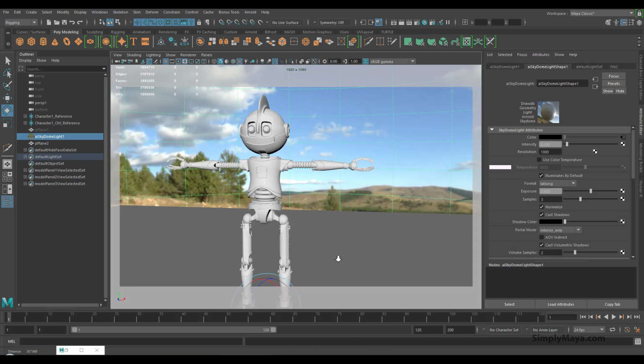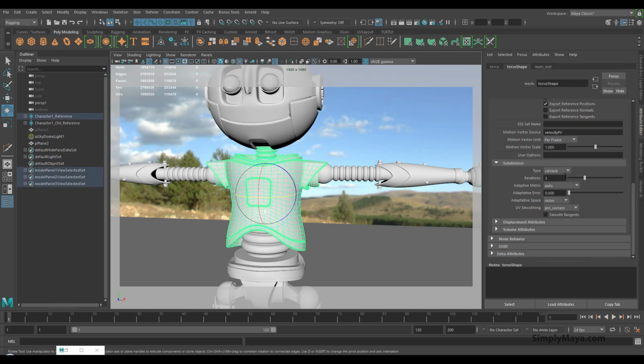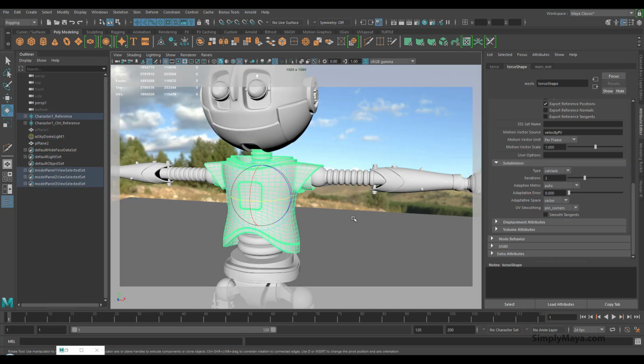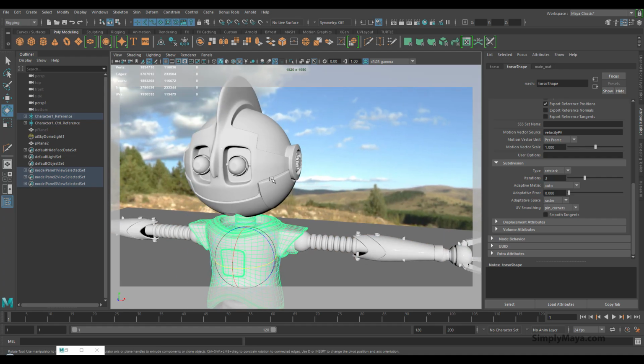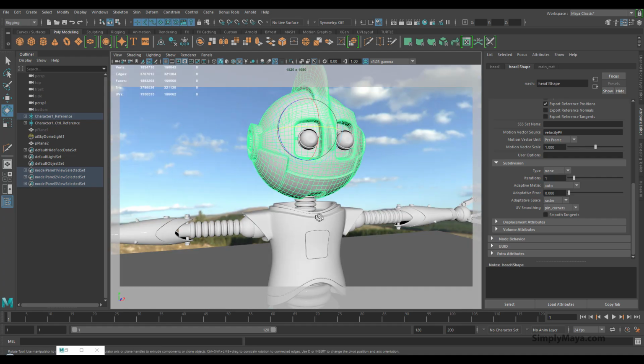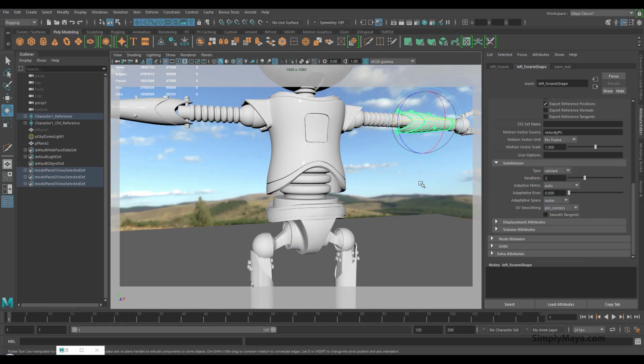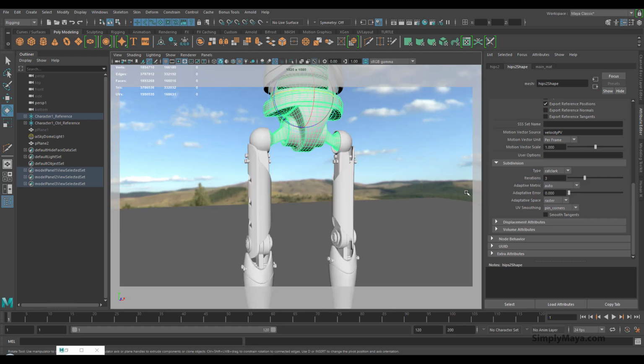Now, close down the render view, and obviously we have some subdivisions on this guy of 3 iterations, but we also have a bit of displacement elsewhere on this model, and we will not have those same subdivisions. So if we go to Catmull-Clark, and I'm going to use 3 for this, it should be adequate for purpose. It can always be turned up later. You'll see I'm just clicking on the geometry here that would have displacement on it and clicking up to 3 iterations. So come down, make sure you get everything with this.